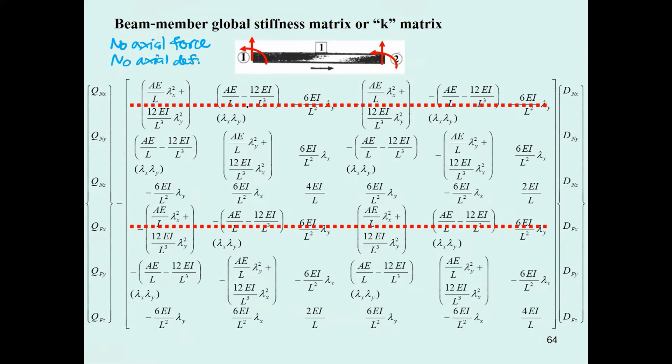So you just cut this portion, and when you cut this one, you've got to cut the first column and the fourth column. You take care of all the ends. On the end is going to be the axial force. Okay, and then you set up this way.